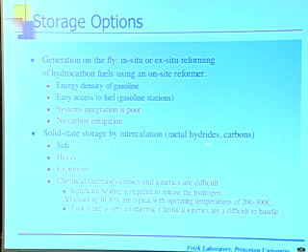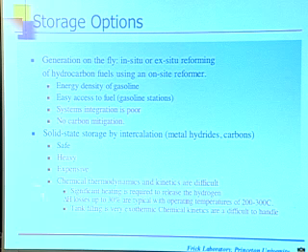One of the favored possibilities now is using a metal hydride, a pure solid state system. Everybody agrees it's safe. Big plus. That hydrogen is not going to go anywhere. You don't need a big steel tank now, but they're metal hydrides. They're metal alloys, so they are intrinsically heavy. You've got a big chunk of metal in your car, so you have a weight issue. Very expensive materials. These aren't your run-of-the-mill metals that we're talking about. That's an issue. The thermodynamics and the kinetics are not working well for you if you want to think about getting the hydrogen in and out of the metal hydride.